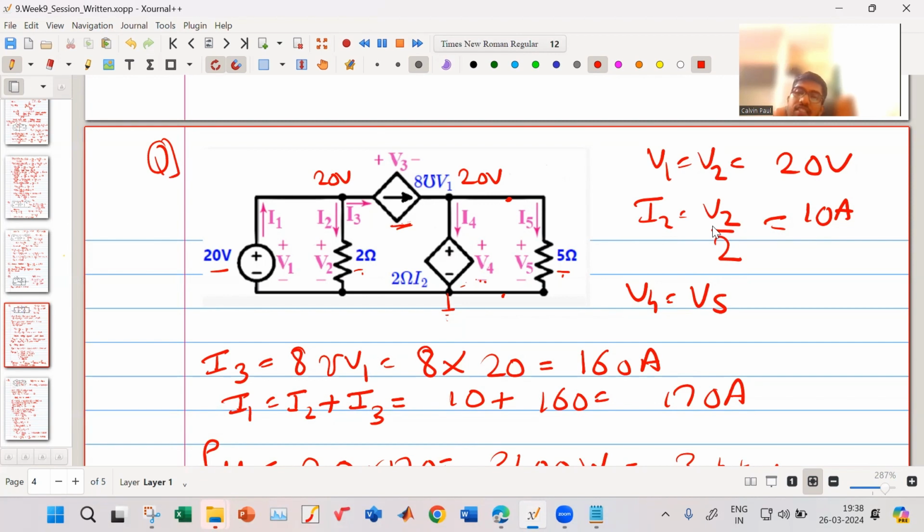it is found in this network, based on these particular values of resistors, the voltage across it is coming to be zero. But in case you change the resistor value or change the voltage source value, the voltage across it may not be zero. And in that case, it will consume power or it might be delivering power.